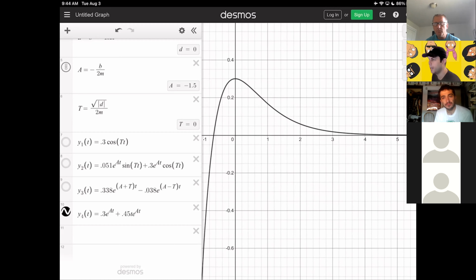That's a road bike spring right there. So notice what's interesting is that's still too long. If I'm a mountain biker, that's still kind of not enough. Now, what does that mean? Does it mean it's impossible to fix it? No, it means you need a better spring. Remember how we put 9 in for the spring constant? That means you need 19 or 72 or some stronger spring. This can't do it. It's too weak of a spring. You can't get a weak spring to get you there.